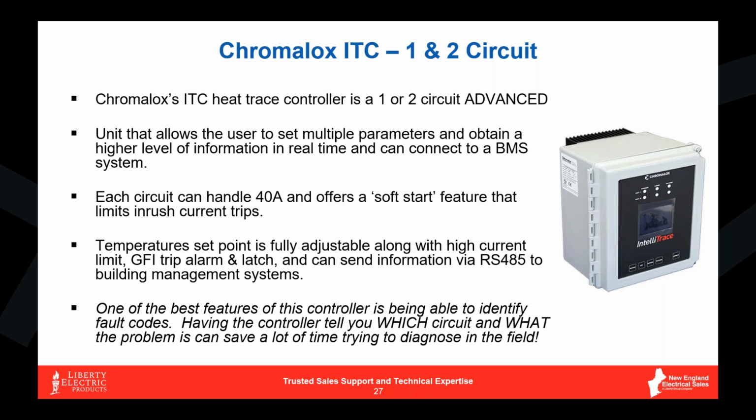But you can run 2 circuits completely independently with their own line sensing thermostat, out of this particular controller. You can also tie 2 circuits together with a single probe or ambient set point, where again, I can kick on 2 circuits with one control, or I should say one sensor. So there's a lot of different options to customize how you want to use this.